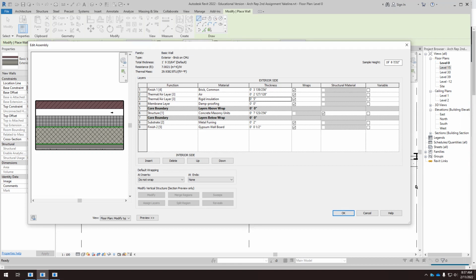We have to pierce the thermal insulation, and then we have to attach this to the solid element. And then if we have a horizontal element like this, another horizontal element like that, like a hook, and then we hang the aluminum layer. It looks complicated, but it's not. It's what you would do in your room if you want to hang your